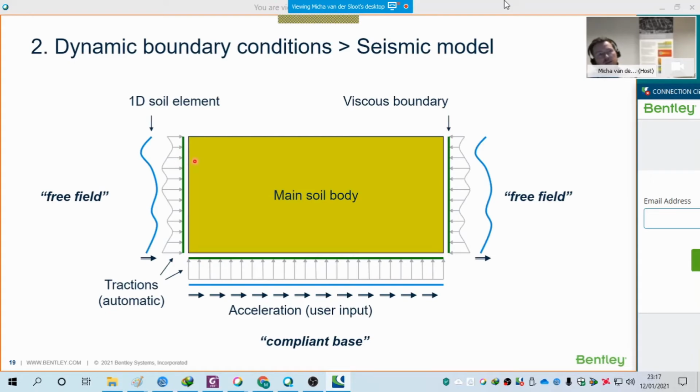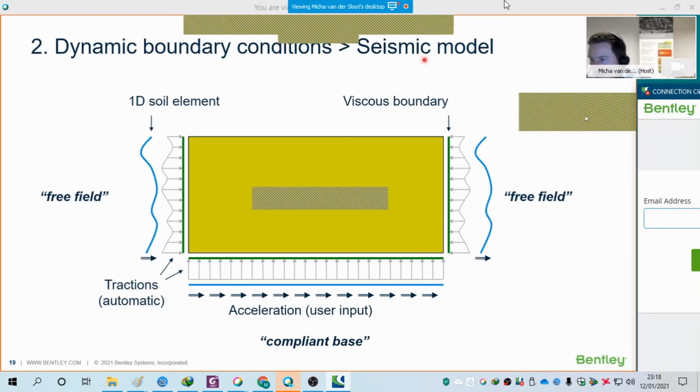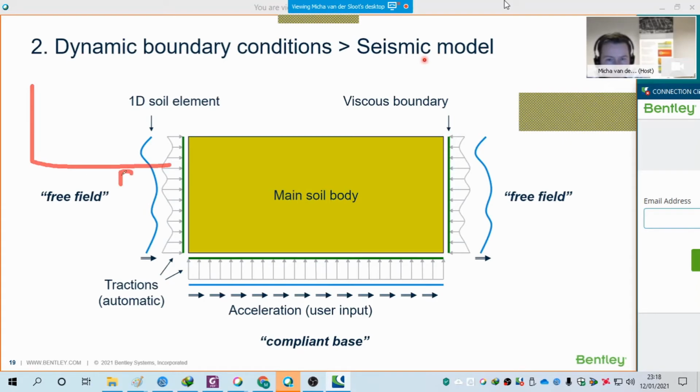But say that you still have a high shear stress, actually you can reach the Mohr-Coulomb failure criterion, for instance. And in that case, what will happen is, maybe I can draw this. So say here we have something in PQ space or sigma tau, it doesn't really matter. Say this would be our frictional failure envelope. Excuse my not so straight drawing here. Say that we start with a stress state here. But due to the seismic event, actually we get unloading behavior. So this will move in this direction. And that means that we're actually touching the failure envelope. And that means we'll have plasticity, and so we will have large deformations there.